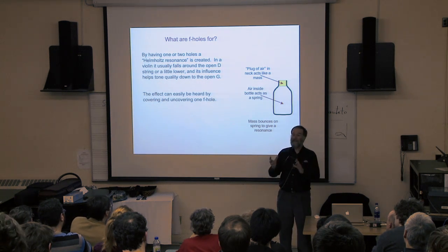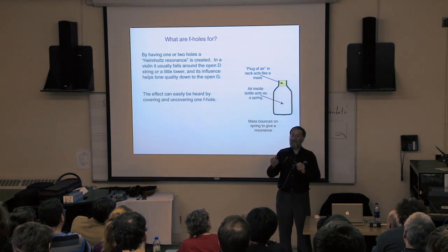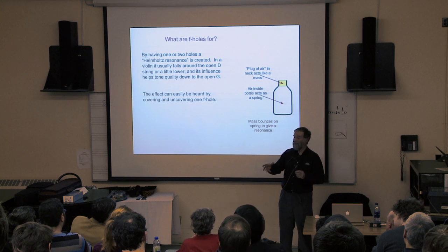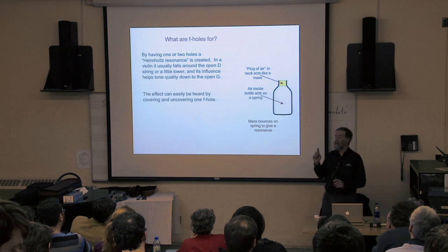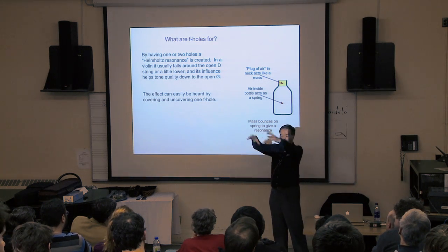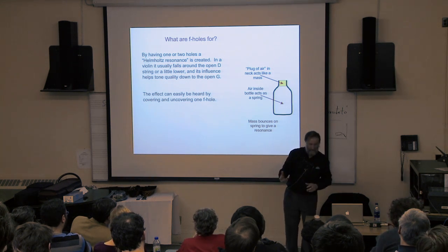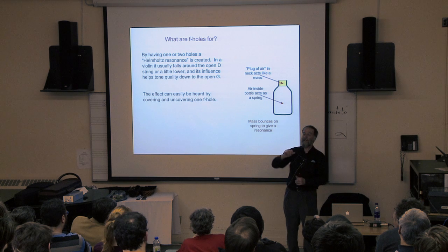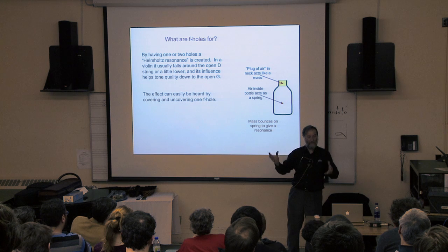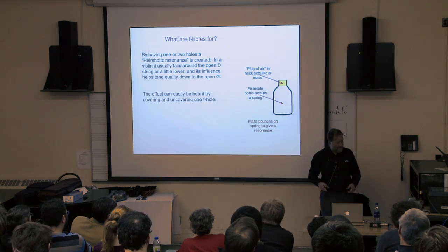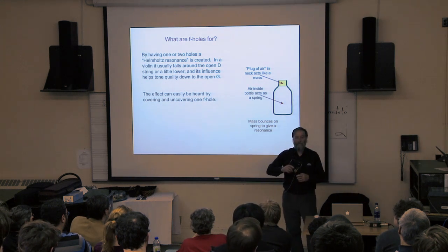Because when you make things smaller, all the frequencies go up. Smaller things, other things being equal, have higher frequencies. It is hard to make a small, conveniently portable but robust thing which has really low resonant frequencies. We have one trick that we can pull out. Because there are good reasons for making our light structure in a closed box because of the structural efficiency of supporting the load nicely, it just turns out that if you've got a closed container and then you make a small hole in it, you can make a resonance which is a different kind of resonance than the ones we just saw animated for the wood vibrating. Something known as a Helmholtz resonance. And it's the sort of thing that you're familiar with every time you do that.